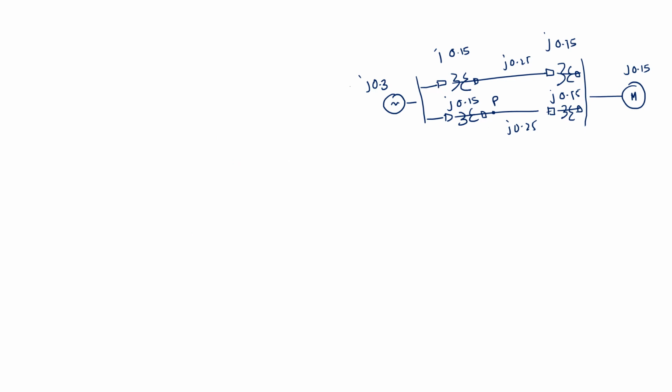Now let us draw all three power angle curves. So let me draw this power angle curve and we will perform the calculations. Let us assume that this is delta and this is the electrical power transferred. So first I will draw the pre-fault curve. This pre-fault curve is like this. This is, I can say, equal to 1.67. So let me mark it clearly.